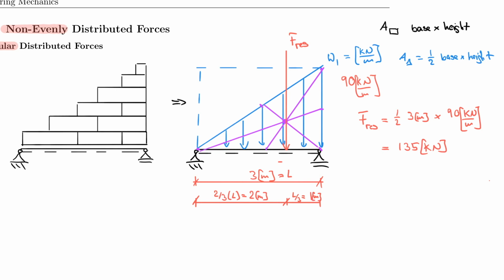So you need to remember this, that the resultant force, the lumped force, A, is calculated by 1/2 base times height, and B is located at this distance, 1/3 and 2/3. And it's important to recognize that what we have here is what I call the heavy side of the triangle, and here we have the light side of the triangle.